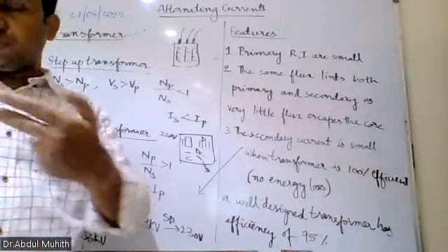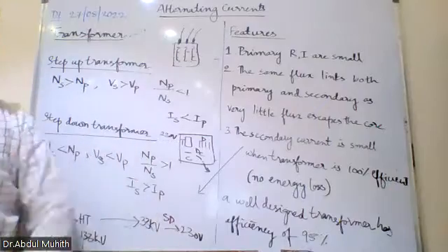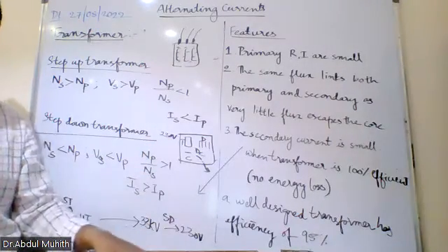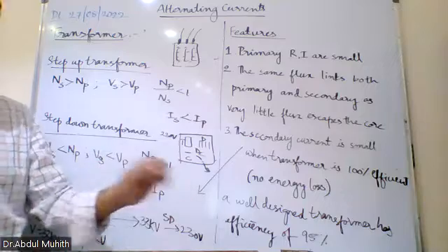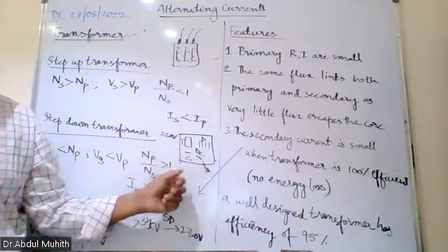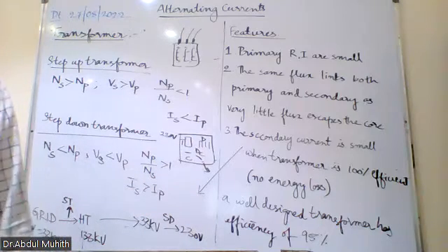The input voltage is AC, 230 AC. Then it will convert to DC. First it will bring down the voltage. The transformer will bring down the voltage from 230 to 30 volt. Then that current goes to diodes and it will filter. The capacitor will filter and give that current to the LED lamp.